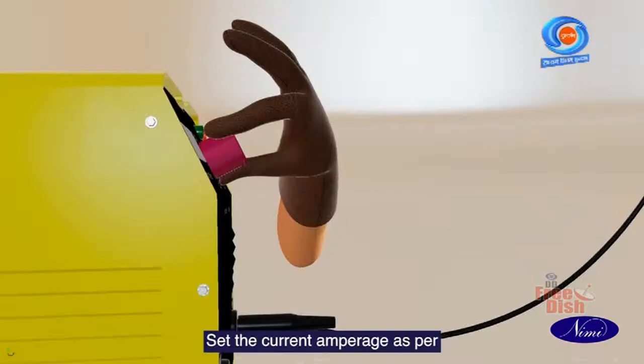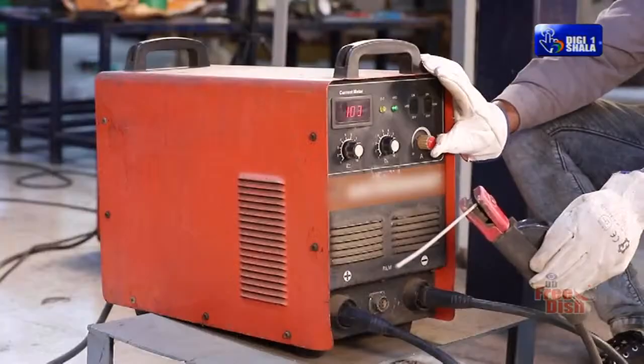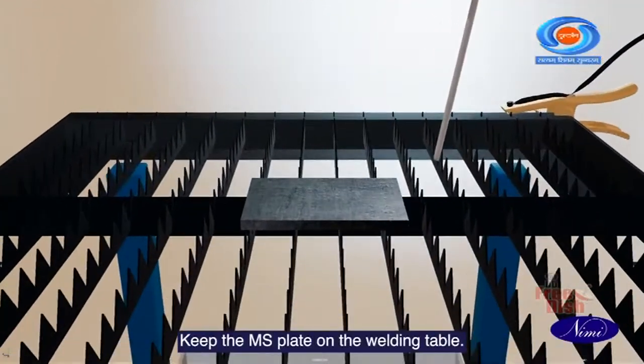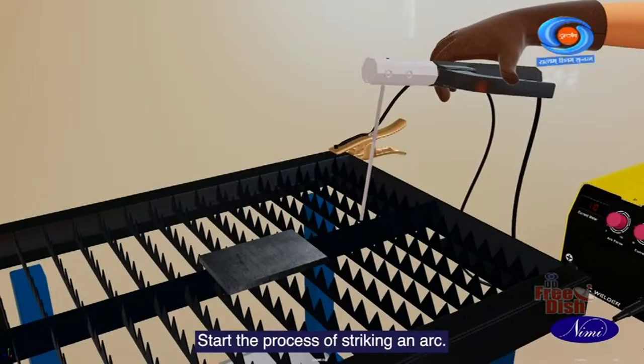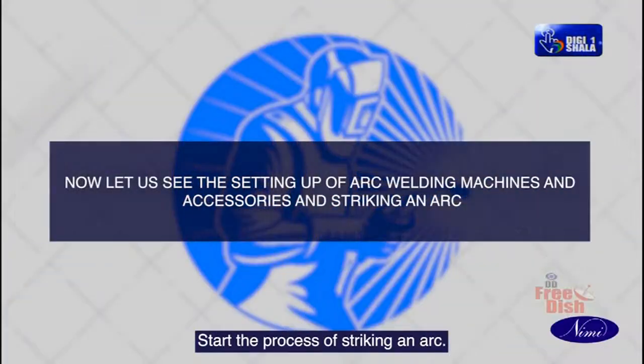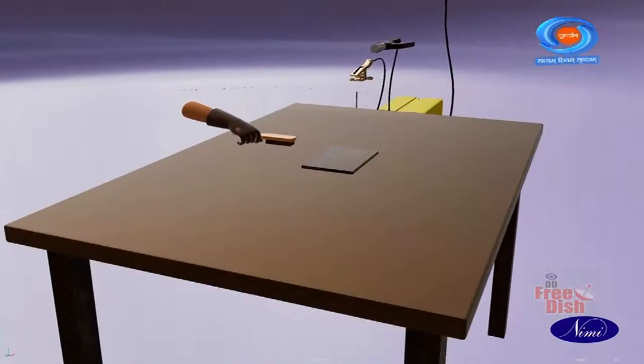Set the current amperage as per the suggested list on the machine. Keep the MS plate on the welding table. Start the process of striking an arc. Now let us see the setting up of arc welding machines and accessories and striking an arc.